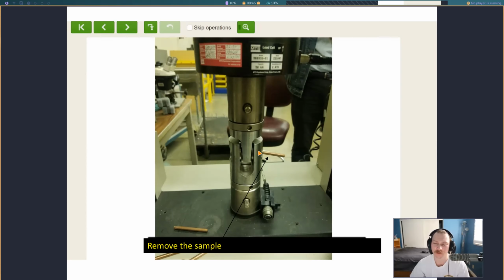In the middle here, we have bearing stress, right? We have the shared surface with the rod in the middle, with this area, this area, and this area. We'll get a better view of that later on. But we're going to get that length, record it, and then use that to calculate the bearing stress. Okay, and then for each material, we're going to test it twice. It's obviously sheared here, but we're going to take the leftover material and test that again, to do this double shear test twice for each material.